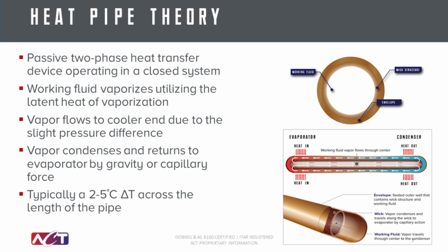When we make a heat pipe, we're sealing these systems. We're pulling a vacuum and putting the small amount of that working fluid on the inside. What this ensures is that that fluid is operating along its saturation curve. So any heat input, even that of you holding it in your hand, causes the fluid inside to vaporize, and that location where that vaporization occurs we call the evaporator. So vaporization occurs at the evaporator.